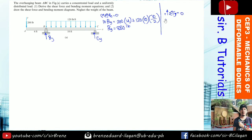So the value of Cy is just equals to 200, and then plus the area of this, 120 times 10, and then minus the By, which is 880. So we will have a value of Cy: 200 plus 20 times 10, and then minus 880. So the answer is 520 pound. Okay, so project it again.